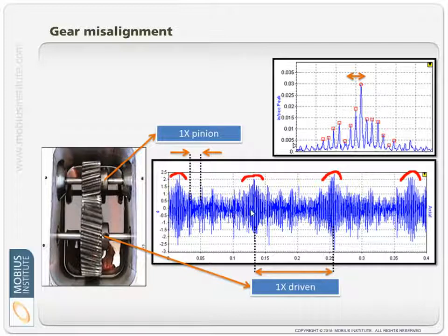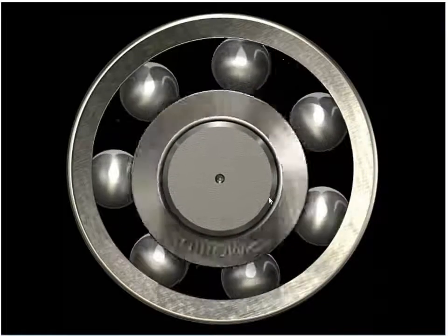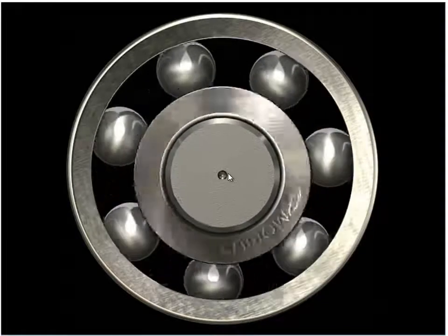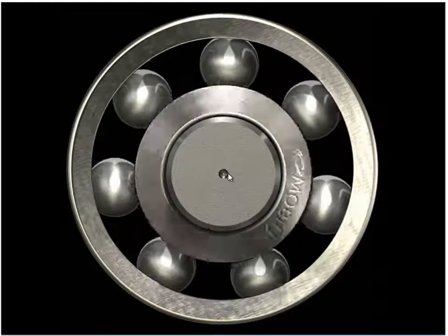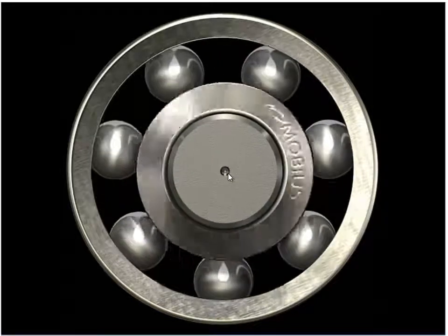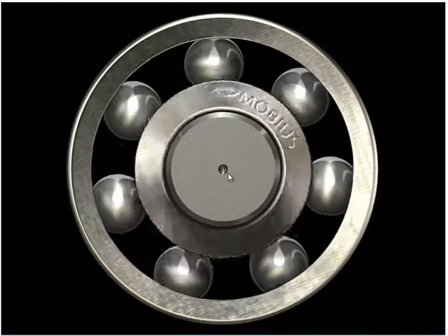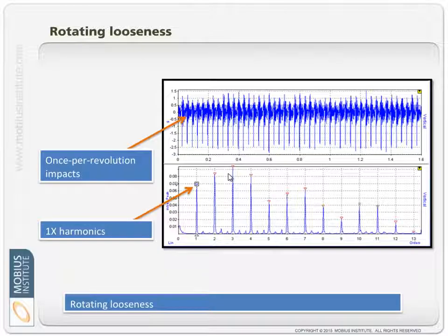When we look at the time waveform, it's telling me exactly what's going on. Here I'm showing looseness. There's the bearing rattling around, or the shaft with the inner race. If you look closely, it's rattling around because there's too much clearance, and maybe there's some unbalance driving that force, that motion. And here is the spectrum. I mentioned it earlier. We've got a lot of these peaks. That's the running speed, twice running speed, 3 times. These are harmonics. So sure, I would see that, and in this instance I'd probably think it was looseness.